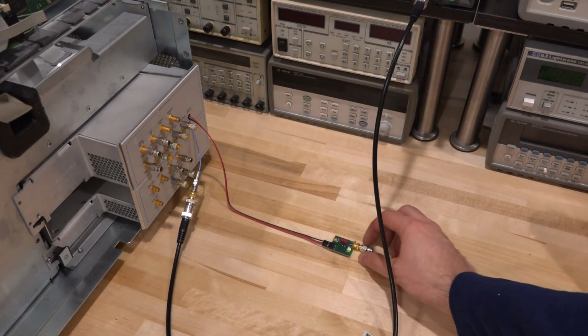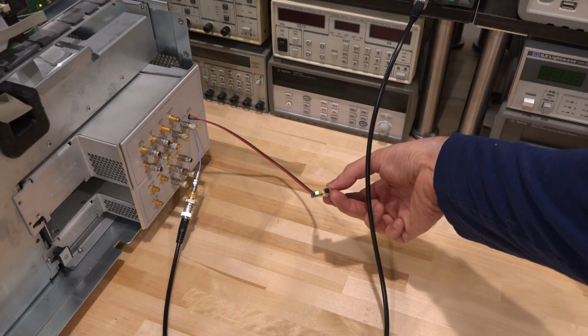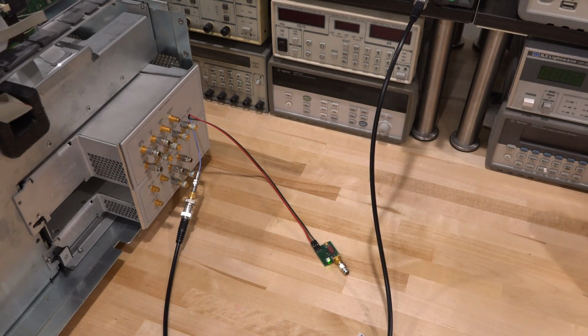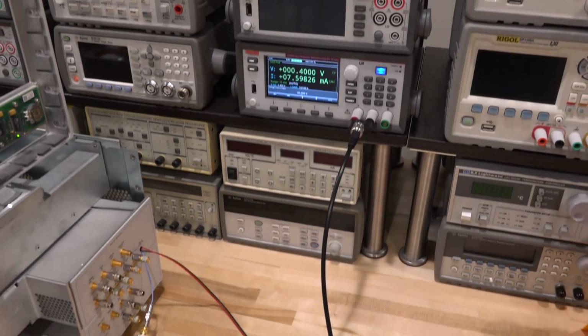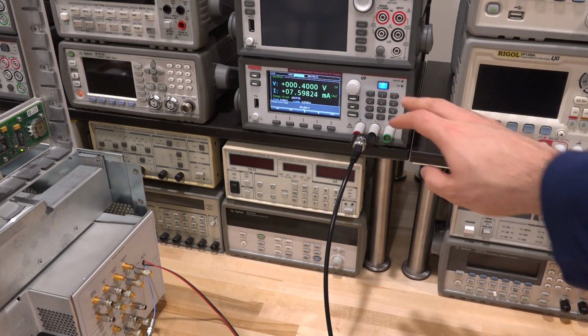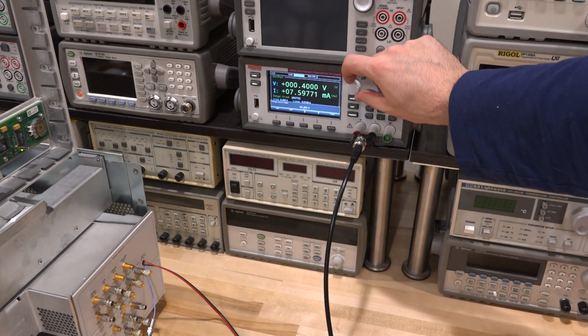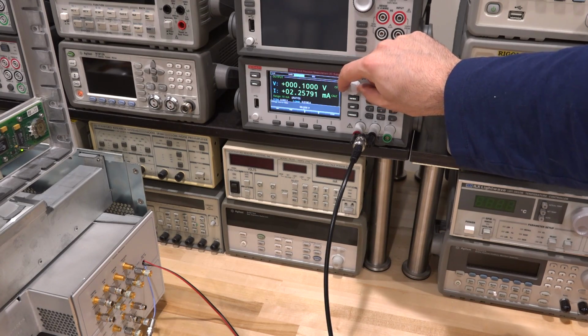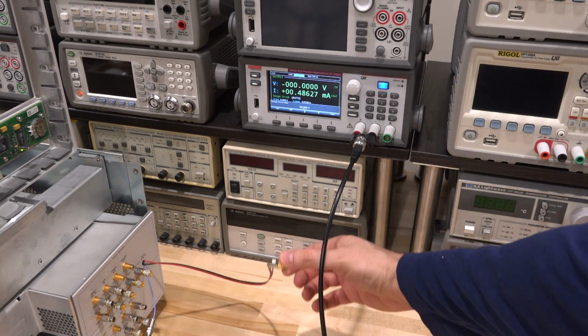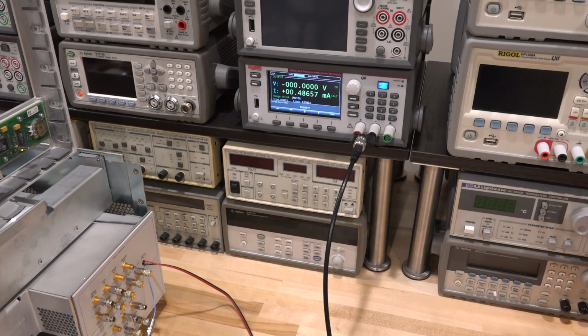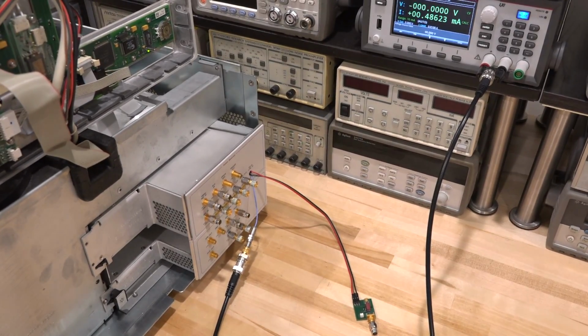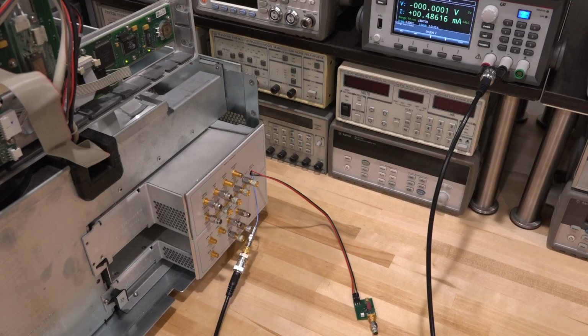And as you can see, the LED does turn on, meaning that the port is now enabled. This means that the detection circuitry is working. It's just misfiring when there is no voltage applied. And unfortunately, this can only mean that the input circuit is damaged. Somehow, some ASIC is being pulled towards one supply, and I'm forcing it to overwrite that by applying an external voltage. In fact, let me go ahead and turn that off, and you can see as soon as I do that, this thing turns off. But since we're already here, we may as well take it apart and take a look at what's going on the inside of it, and perhaps there is something that we can do.